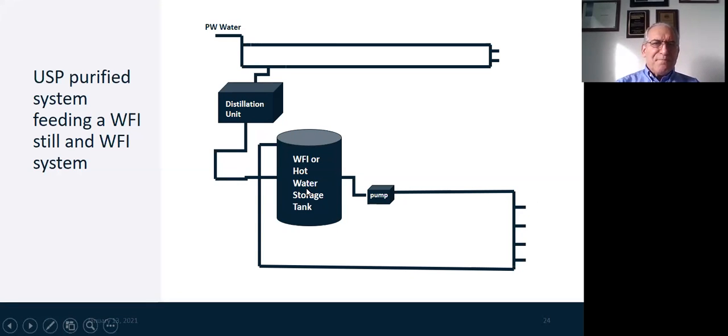water storage. The point is that both the purified water loop and the hot water loop, especially if the purified water loop is heated for a hot water sanitization, are susceptible to rouge, and both will need derouging and passivation over time.